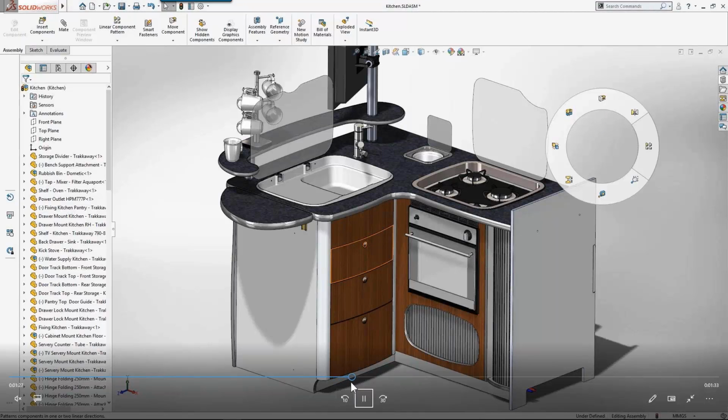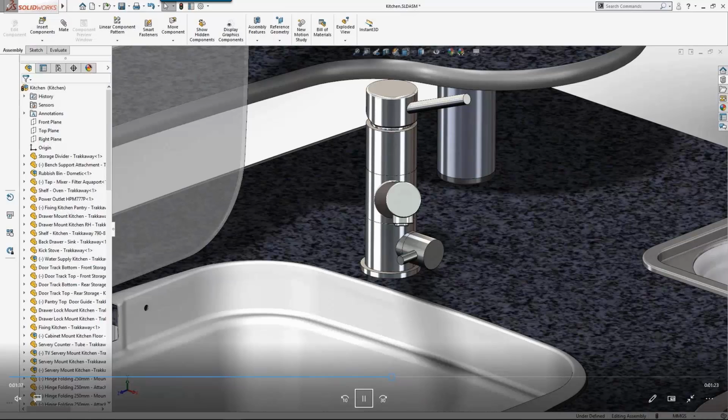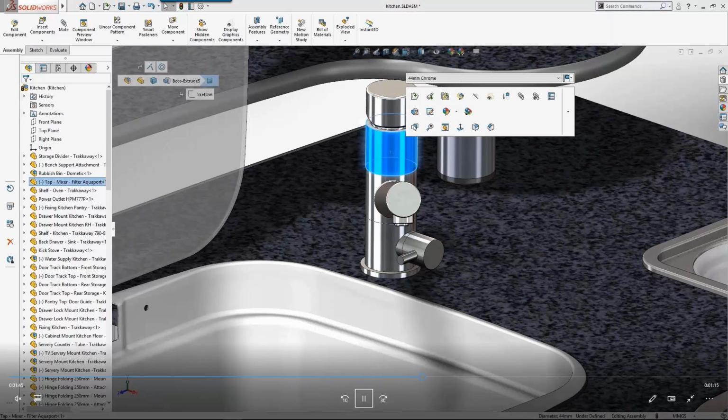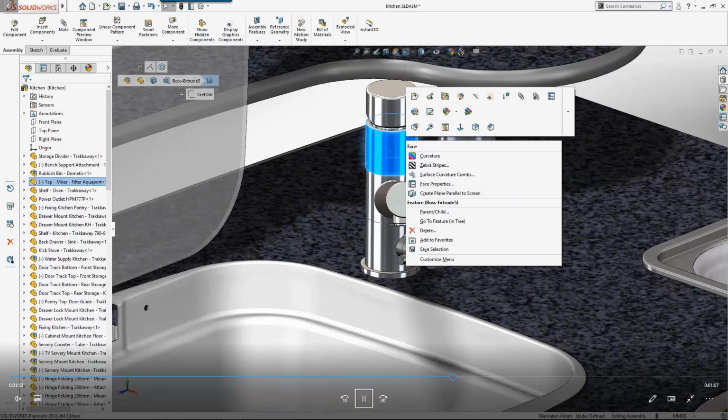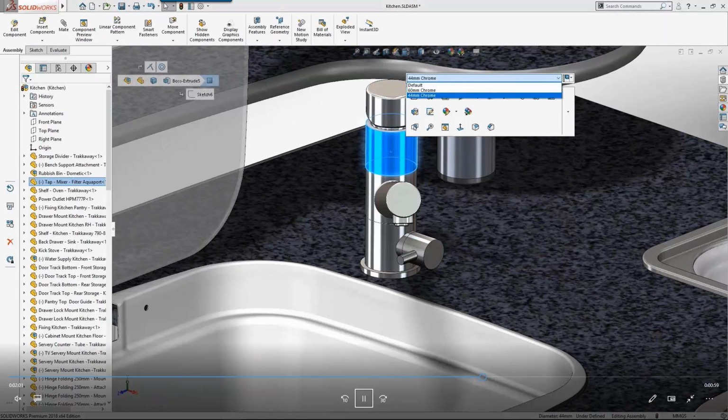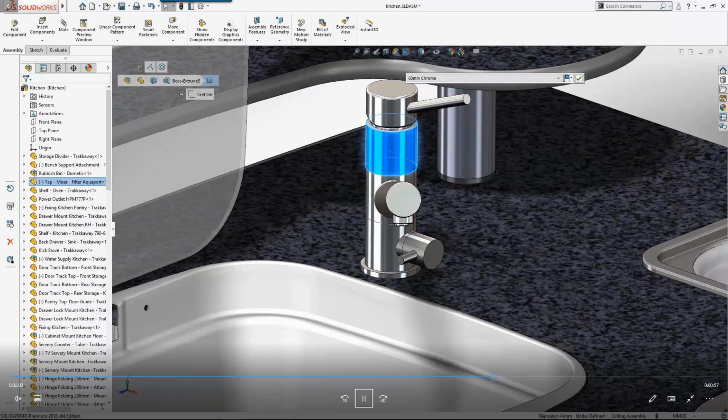When working with touch mode, mouse gestures are another great way of accessing frequently used commands at your fingertips. With an on-screen finger press and drag, the mouse gesture ring can be displayed. Next, simply move your finger over the desired command and activate it. To bring the tab closer into view, we'll first select zoom to area, followed by the finger swipe to define the zoom region. Making modifications to design is easy using touch interaction in 2018. It's quick and intuitive. For example, changing the configuration of this tab to a larger size.